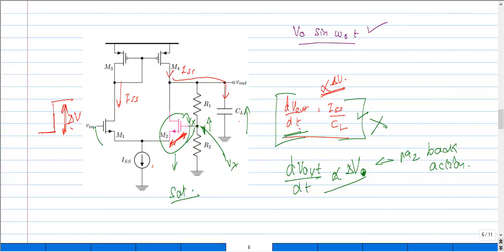Like we have already seen in our AMC classes, that value should be equal to V naught times omega naught. So I need a slew rate equal to V naught times omega naught, so that any signal whose frequency and amplitude are of this magnitude can be cleanly amplified. The output would then correspond much more to our linear circuit.